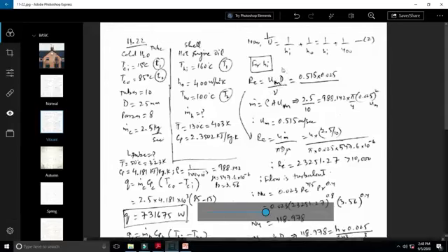Reynolds number can be written either in this form, velocity into diameter upon viscosity, or it can also be written in this form, 4 times mass flow rate over pi d mu. And I had shown you in chapter 8 how we can get from this point to this point. I mean, we can come from this point to this point by putting the velocity in this form, as mass flow rate, using the continuity equation, simply saying.